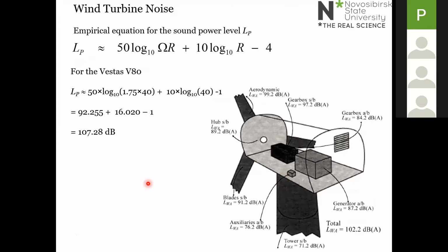It's a very, very simple example of noise calculations for a wind turbine. Noise assessment or noise computation is an incredibly complex task. If you're going to do it properly, it requires time-resolved, three-dimensional computational fluid dynamic simulation of the flow over the turbine. It's extremely complex. Most of the noise on a turbine, and that's what this old image is meant to show, is aerodynamic noise. In other words, noise that is caused by moving through the atmosphere.